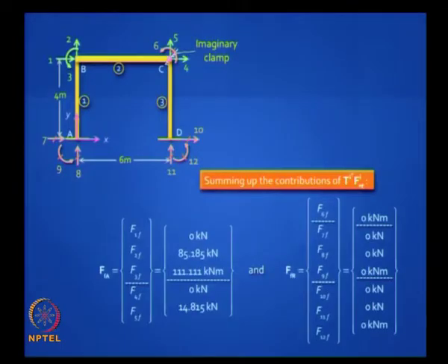What do you do after you find the fixed end force? You have to convert to global coordinates, and after that get the net load vector or the resultant load vector. So how do we do that? We do it by Ti transpose F star.